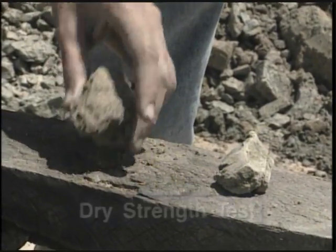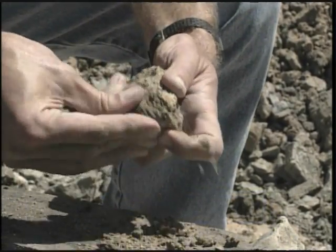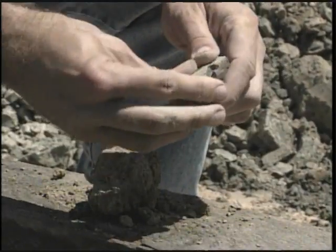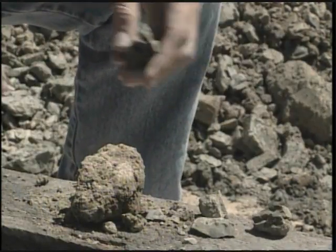Another test is the dry strength test. If a dry soil sample crumbles on its own or with moderate pressure, it's granular. If it crumbles into smaller clumps that resist pressure, it's cohesive.